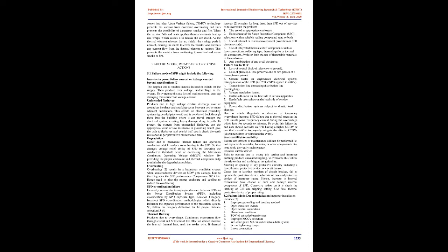6. Thermal runaway. Produced due to overvoltage and continuous overcurrent flow through the circuit, and the SPD end-of-life effect on the device increases the internal thermal heat and melts the solder wire. If thermal runaway remains for a long time, then the SPD goes out of service. So to overcome the problem: 1. The use of an appropriate enclosure. 2. Encasement of the surge protective component, SPC, selections within suitable sealing compound, sand, or both.